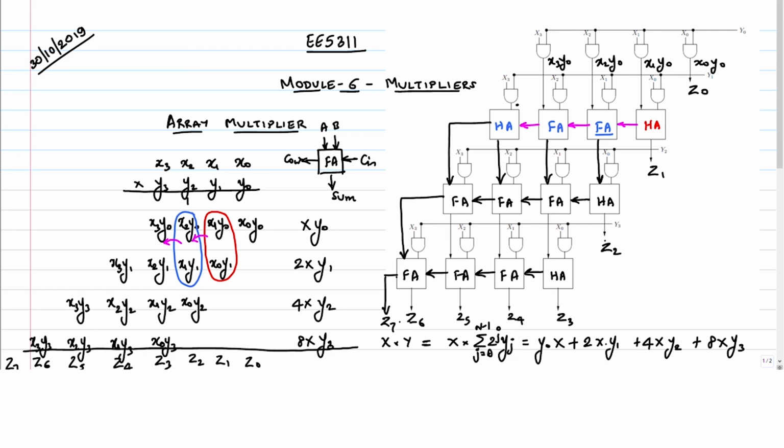Right? So this basically tells you how to line up an array of full adders, right? Even the half adder I can consider a full adder, right? When you're trying to make an array structure, you don't optimize on that area there. You take a full adder and repeat it. I'm just calling it half adder, full adder so that it makes it more clear. Okay, otherwise they're basically just full adders.